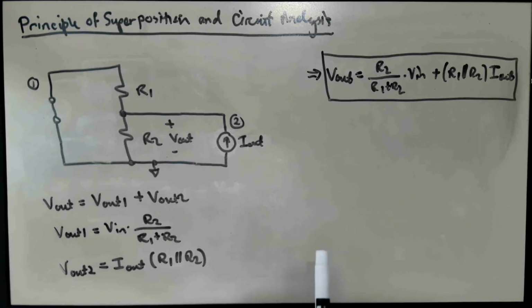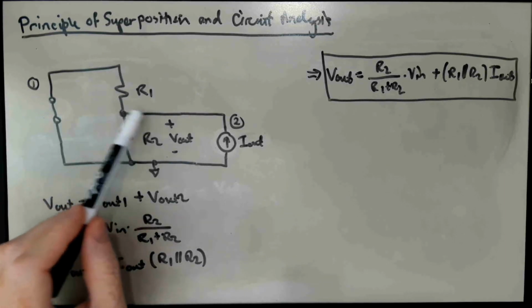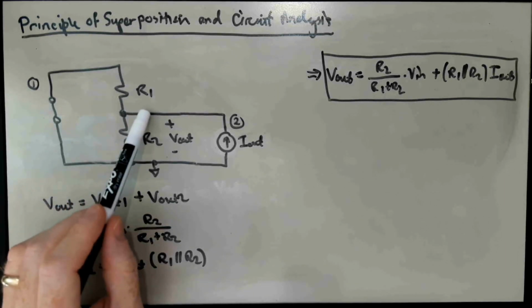But this is actually quite a practical thing as well. We work with voltage dividers all the time, and it's a way of creating a reference voltage someplace from a power supply that may not have the value that we actually want. But all the time, we wind up assuming no current flows out of the middle node.